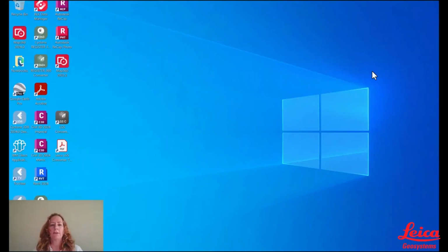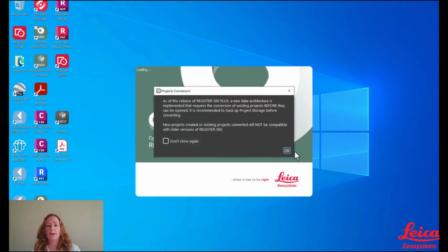Welcome, my name is Karen Hughes. Today I will be showing you how to prep your point cloud data so it is ready to create a 3D model. Once the data is collected in the field and downloaded, it is ready to be imported into Cyclone REGISTER 360. Launch the program and create a new project.